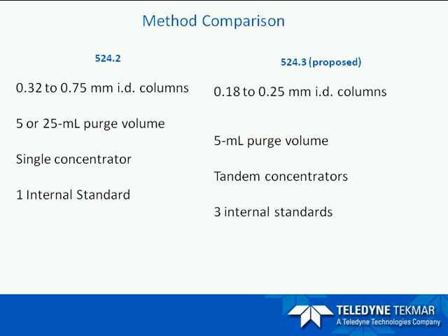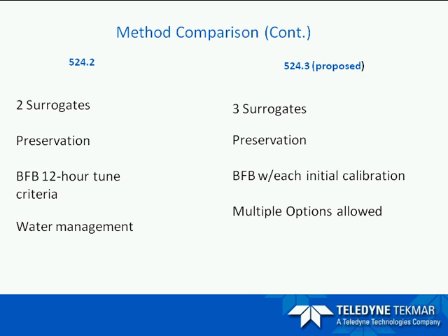1,4-difluorobenzene D4. They've also investigated the use of different traps that had not been previously available when that earlier method was published, and they have included that in the new revision. They've also made some mention of new column and instrument recommendations and conditions that may be permissible. And this is because of the new updated reflections on the state-of-the-art techniques available for both GCMS as well as purge and trap concentrators now available. Now, in method 524.2, if you remember, there were 2 surrogates that were used.